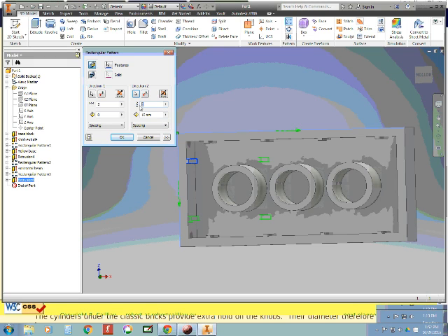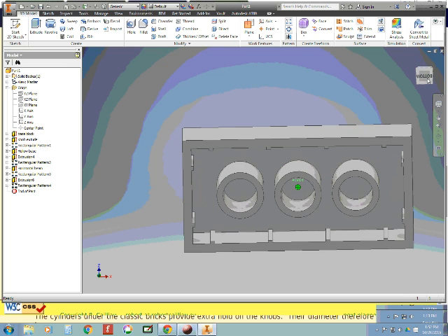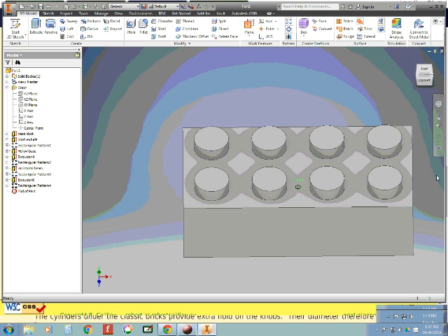So let's take a look at that. It's, whoops, we got 2. Make this 31.8 minus 1.2 for one wall thickness, minus 1.2 for the other wall thickness, minus 0.3 for the thickness of that extruded feature of the beam. I click on OK, and my Lego brick is done.